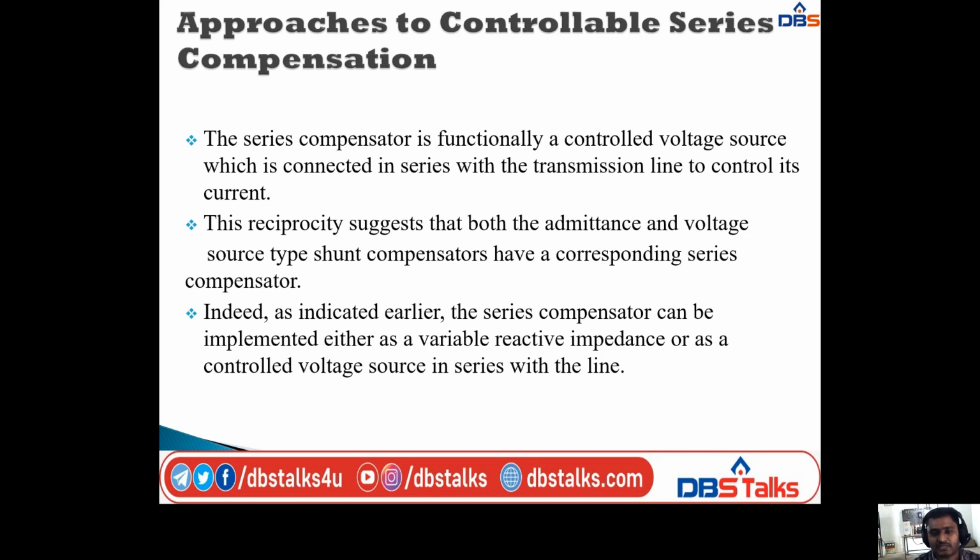This reciprocity suggests that both the admittance and voltage source of shunt compensators have a corresponding series compensator. So indeed, as indicated earlier, the series compensator can be implemented either as a variable reactive impedance, or as a controlled voltage source in series with the line.